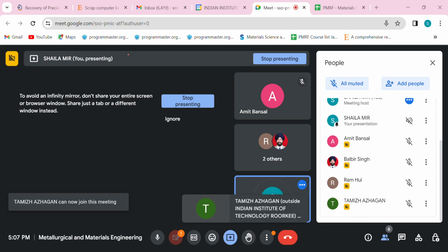In the first stage we are undergoing strain hardening. Then in the second stage, recovery of the strain hardened material occurs, because if you increase the temperature above the recrystallization temperature, some stresses inside the material are removed and the grains become stress free. That is called recovery. After that, if you increase the temperature further under a constant load, it will result in necking, or fracture of the material. So option C is right.